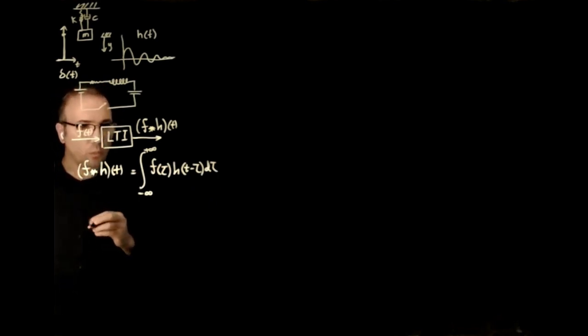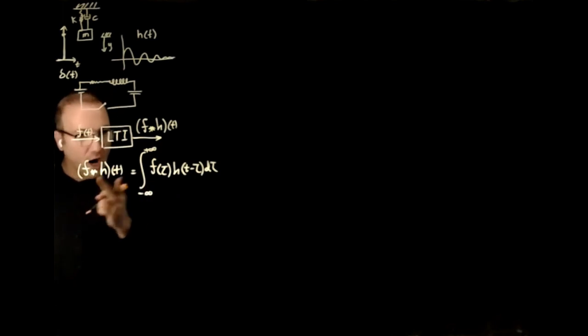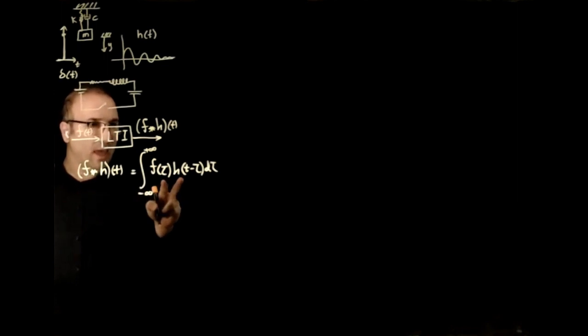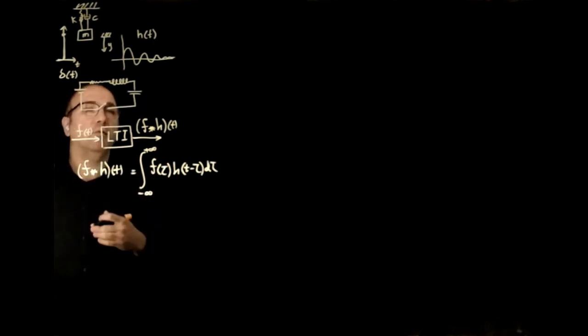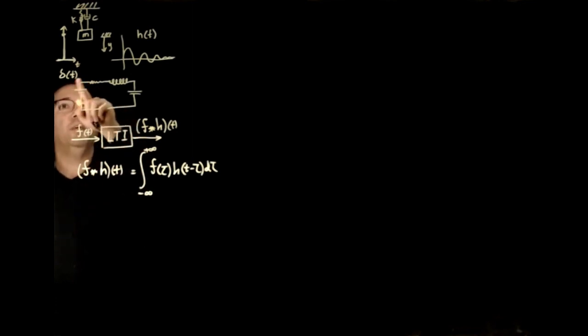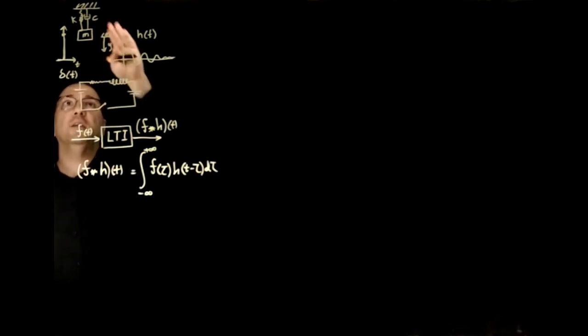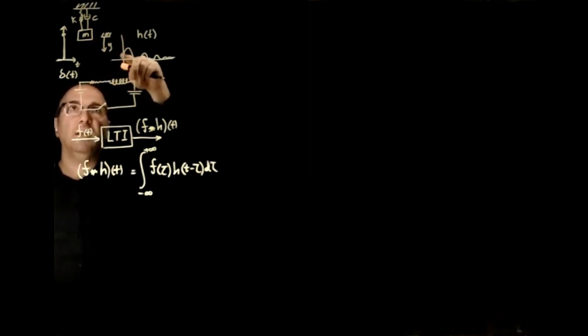So we want to discuss why this is true, why, if we know the impulse response, that is true, and what is this convolution. For now, assume that our system is causal. So every physical system is causal, meaning that before the delta starts, h wouldn't start. So the delta starts at time 0, any input would start at time 0, and the output wouldn't start before the input. So it's like we are saying that before I tap into that, it wouldn't start oscillating.